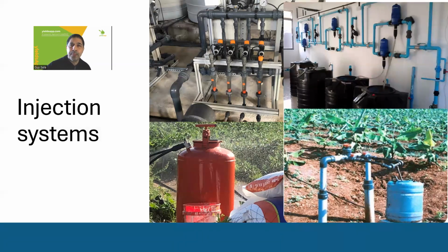It's the same. So here we have injectors that take a concentrated fertilizer solution from a tank, and inject it proportionally, right, into the irrigation water. And here comes the concept of injection ratio. There was a question about it. Okay, for example, injection ratio, the easiest way to understand it is to talk in terms of percentages. So, for instance, 1%, all right, here it's a mechanical system where it doesn't require electricity for the injection, for the irrigation, of course, it needs a pump.